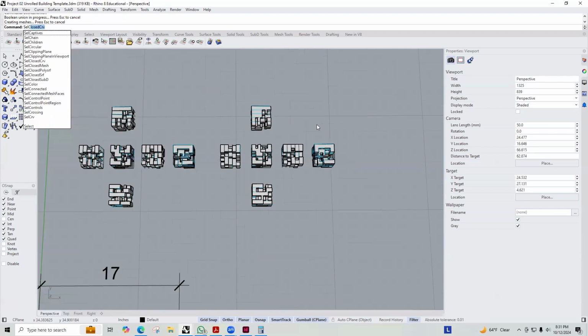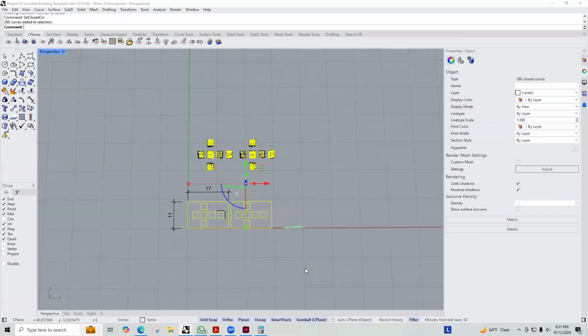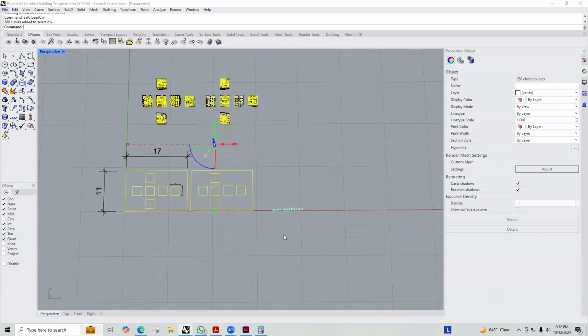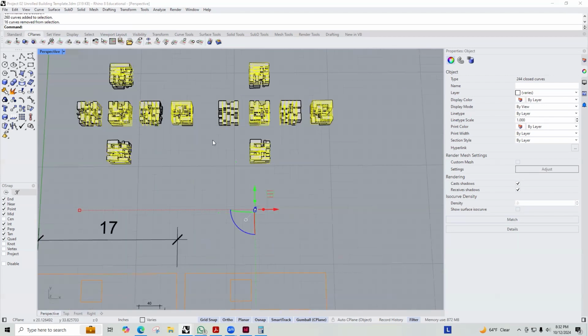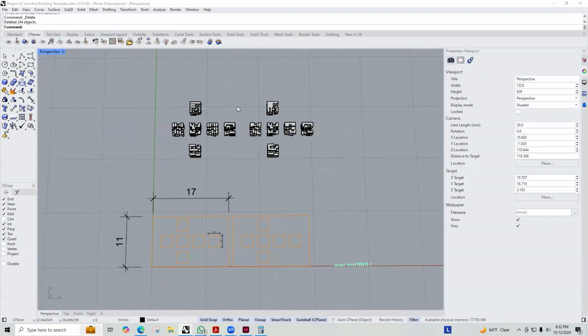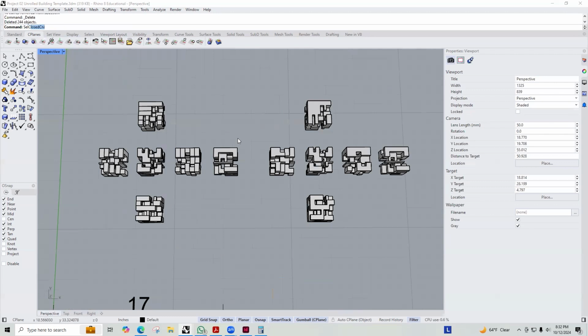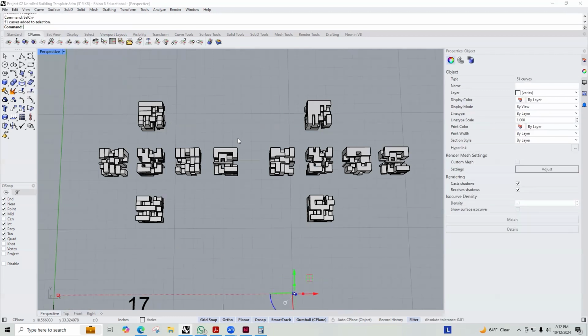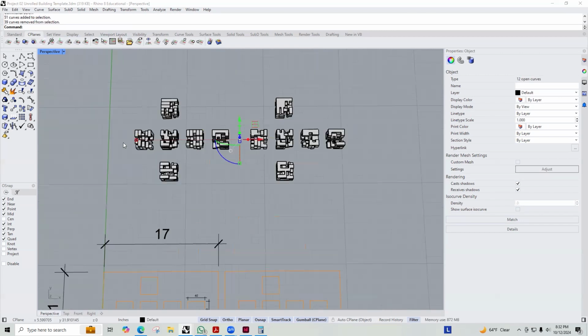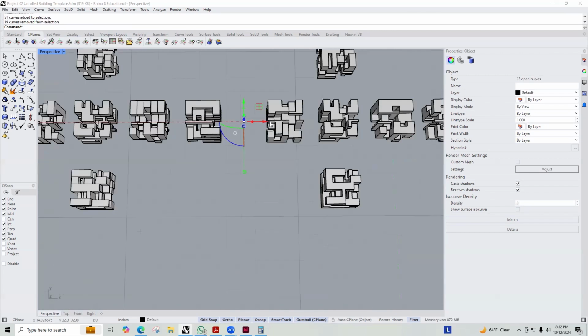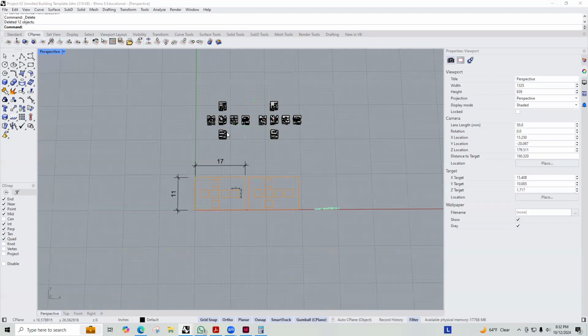So I'm doing select curve. Select closed curve came up first, that's fine. Deselect the curves that we're keeping. So I just pressed Control and I drew a window over the things that I'm keeping. And I pressed delete. All right, so now I just want to do a general select curve. And I want to make sure that none of these are included. And you see I have some straggling curves in here. So those are now deleted. Great.